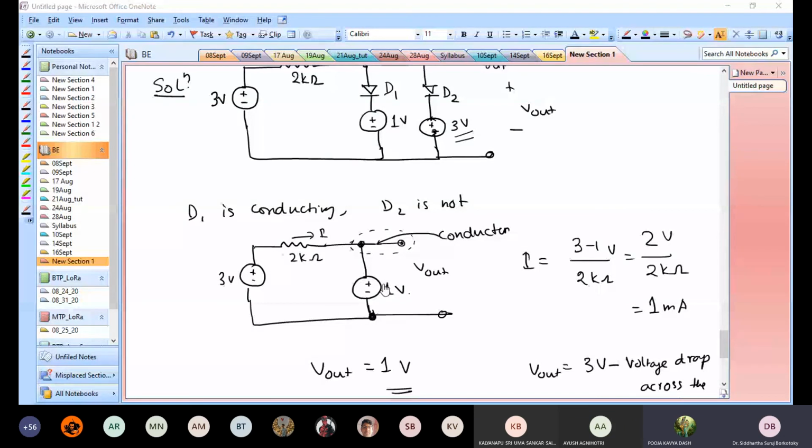No, I mean, suppose you have an RLC circuit and you are trying to get the output across R. It does not matter whether the capacitor is first or the inductor is first, as long as they are there somewhere. You'll get the exact same output.